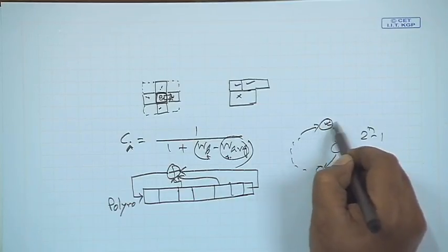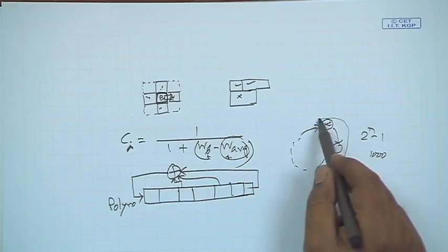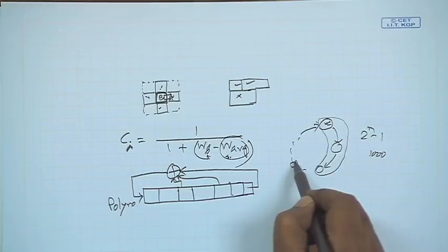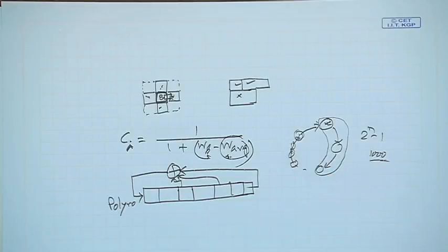If you start here and run for 1000 cycles, you will get some set of patterns. If you start at this point and run for 1000 cycles, you will get this other set of patterns. So depending upon the seed value also, the sequence generated will vary. As a result, the fault coverage, power consumption, temperature, everything will change. So that is another parameter.